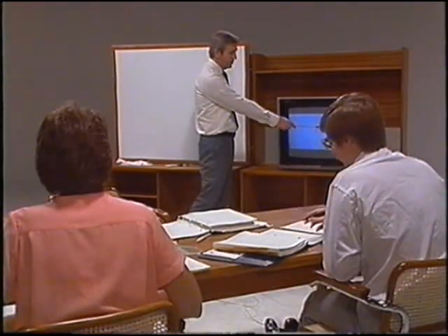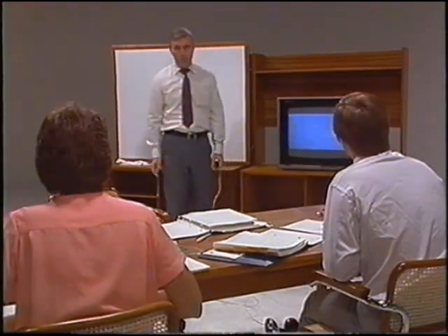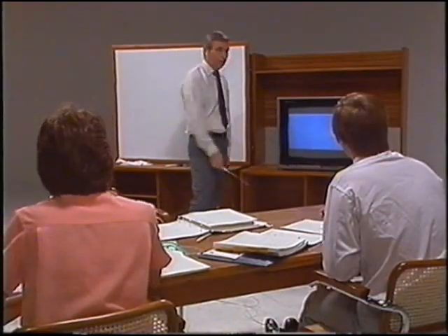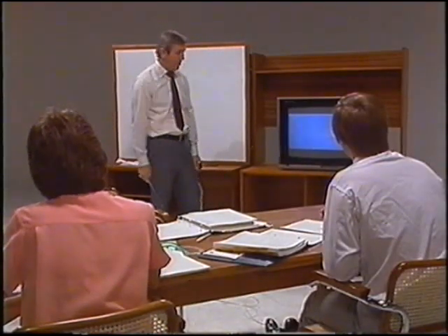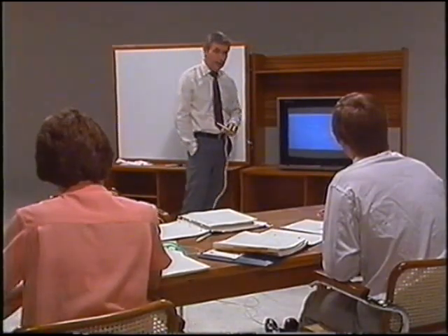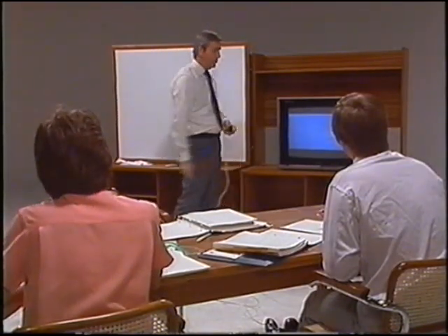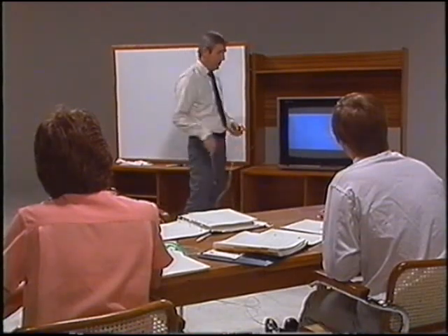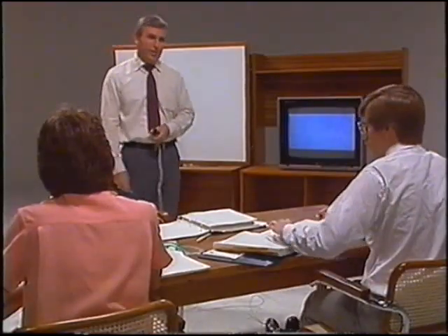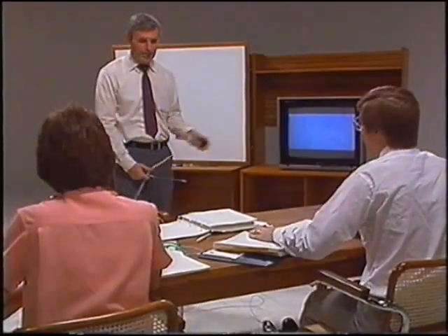This quantity right here is a function of the medium and the properties of the fluid, and it does not vary very much. We've already said that critical velocities are usually much slower than actual rates. So what we're saying here is that the critical wavelength is essentially driven by the velocity of propagation, the reciprocal of the superficial velocity. And for a typical rate, 0.06 meters per day, I get a critical wavelength of about 2 centimeters, which turns out to be the case on almost every case you choose to calculate.